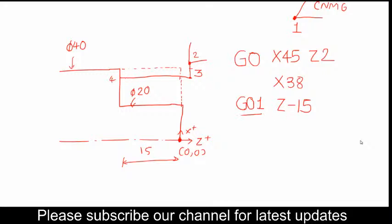And since it is G01, we have to define the feed. I'm defining the feed rate as 0.5. I can write 0.4 also. Here the unit of the feed rate is mm per revolution, so every revolution the tool will move by 0.5. Since it is a rough cut, I would opt for that. If it is a final or finishing cut, I should opt for a 0.1, 0.15 or 0.2 feed rate. Okay, so I just wrote 3 lines and 4.